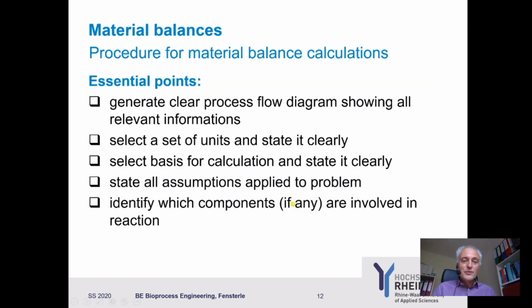Now we had of course a very simple balance at the beginning. We start simple, but of course if the processes get more complex, also the balances and the demands for solving the balances get bigger. What is essential if you want to start to solve more complex problems? The essential point is, first of all, generate a clear process flow diagram showing all relevant information.